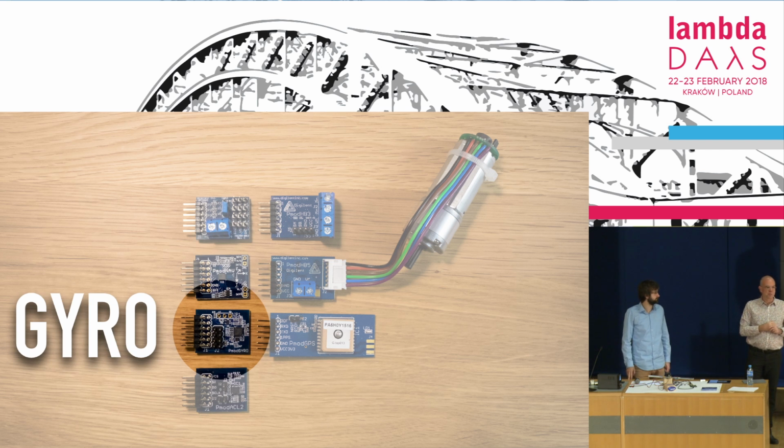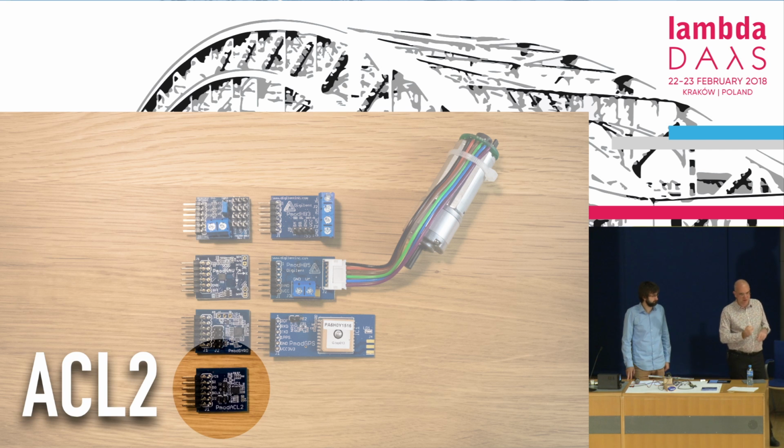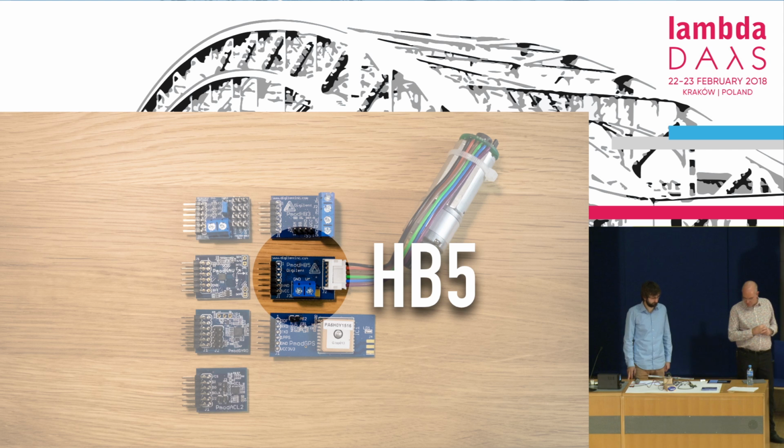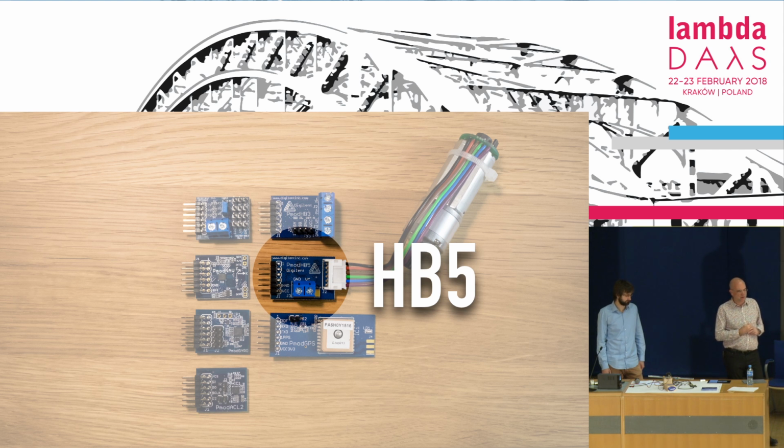There are also Pmods which just implement the 3-axis gyro or just an accelerometer, but I would recommend going for the Pmod NAV because we have a very extensive driver for it, and it has everything you would ever want for inertial measurements and location things. There are also lots of different motor driver Pmods. Those are the H-bridge Pmods, so you can wire up a higher powered motor to it.